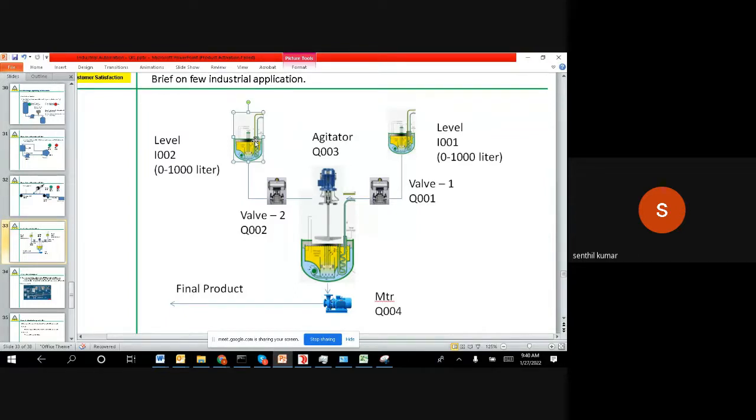One reactor contains one motor to stir the whole liquid inside, so that you get a homogeneous output. And then you have the jacket for cooling. The cooling temperature, the steam will go inside to heat up the liquid. And then sometimes they will have the pH control, where they add acid or base to achieve the expected pH, and that's it. So with all this combination, they try to keep the product for a while.